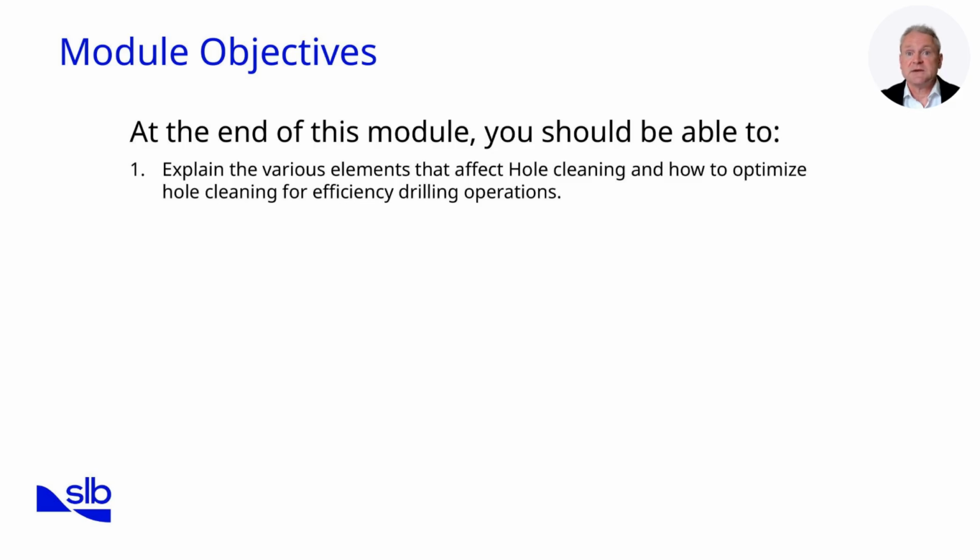Next, we will study the relationship between cleaning rate and hole inclination, referencing findings from Ocrogini's SPE paper on mud cuttings transport in directional well drilling. This will allow us to understand how well trajectory impacts hole cleaning efficiency, particularly in deviated or horizontal wells. We will then move into drilling fluid properties, including density, rheological characteristics, filtration, solids content, and chemical composition, all critical to designing a fluid system capable of effective cuttings transport.